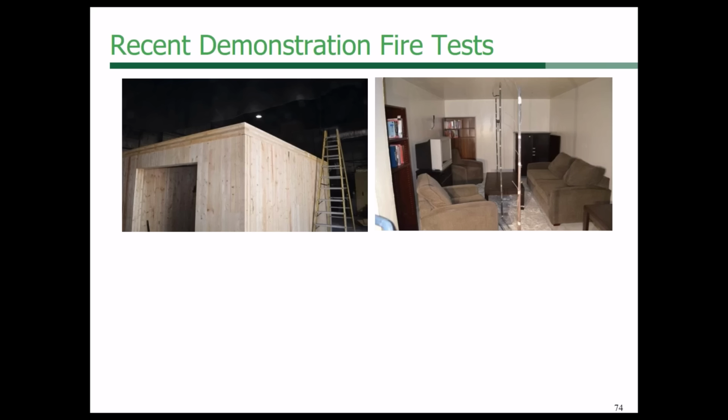a compartment fire test, estimated to be about 95% of modern residential fuel content loading. You can see on the right all the amount of furniture, that's the fuel when the fire is started. And the cross-laminated members that were used were manufactured using ANSI APA PRG 320.